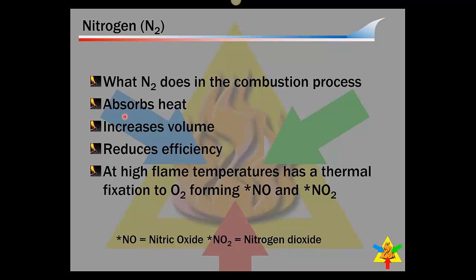So if we have a lot of excess air, or nitrogen by default, it'll start to reduce the flame temperature dramatically. A good example of this is natural gas, when burned in any combustion appliance in the Earth's atmosphere, will have a flame temperature of about 3,500 degrees. If you could take that same natural gas and burn it in 100% oxygen with no nitrogen in the mix, your flame temperature will be well over 5,000 degrees. That's the effect that nitrogen has on the system. And so we have to be aware of that fact because we deal with this thing called excess air.